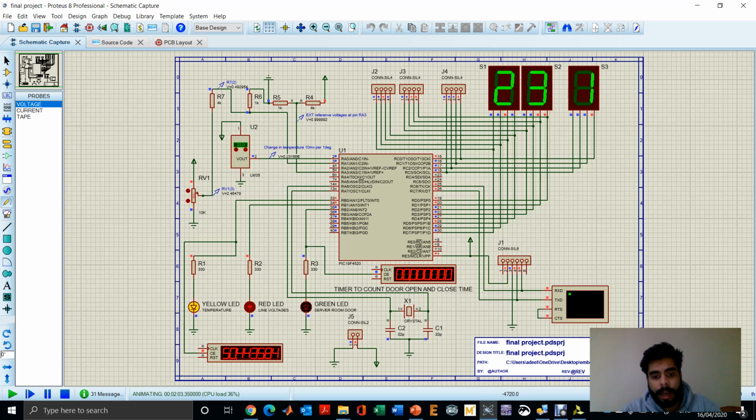So we can see my code is working very accurately, and the maximum voltage that we can obtain from here is 1 volt. It will not go more than 1 volt because of the voltage divider scheme I have used here. We can see 5 volts here, but the system will not go more than 1 volt, otherwise it will potentially get damaged when you are building the hardware.